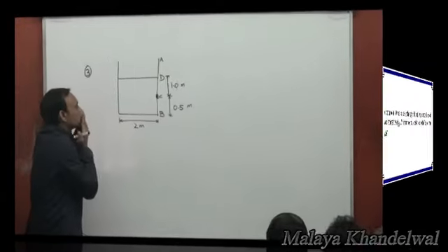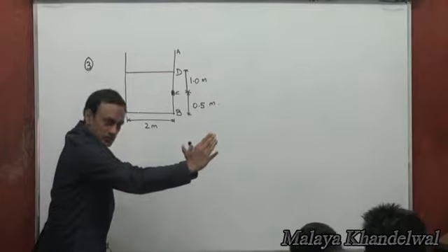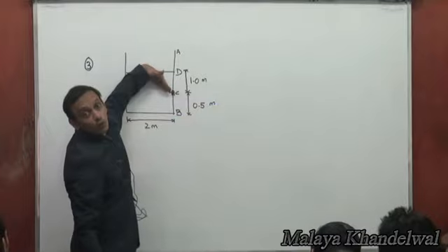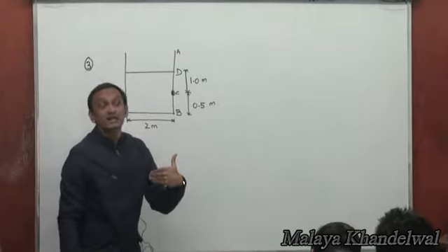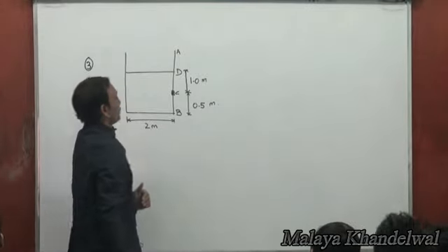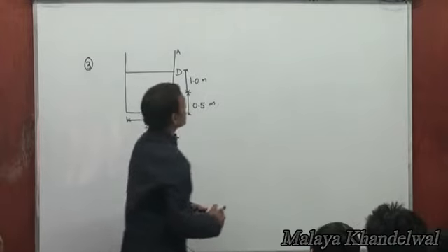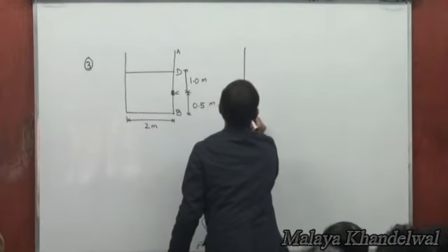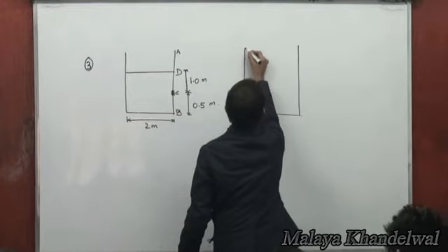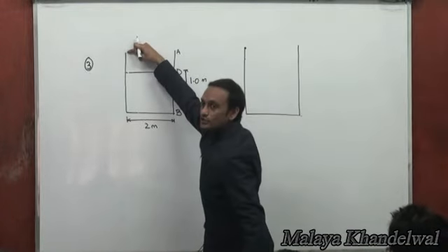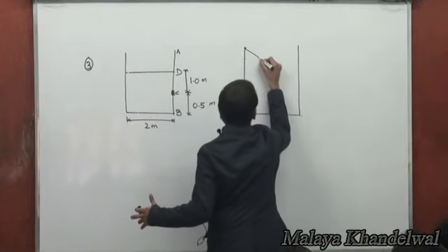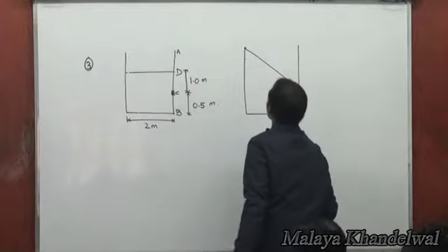When the container is imparted a rightward acceleration, the water level will acquire an inclination with the horizontal, theta, such that tan theta would be a by g. Now, in a limiting situation, when things have spilled over, we're going to have this just about reaching the highest point. It can't go higher than this for a complete spillover, right? So then the spill goes down to this level.